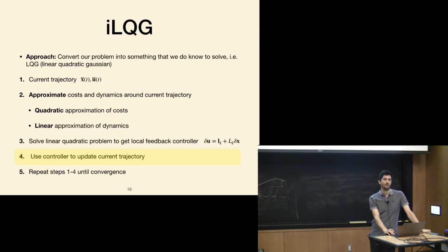I think it's pretty similar. Yeah, I mean, if you think about internally what a nonlinear optimizer is doing, it's pretty similar, right? Like SQP is very much a quadratic approximation of the cost, linear approximation of the dynamics. It's pretty similar. This is doing trajectory optimization. iLQG, in the case of known dynamics, is a trajectory optimizer.